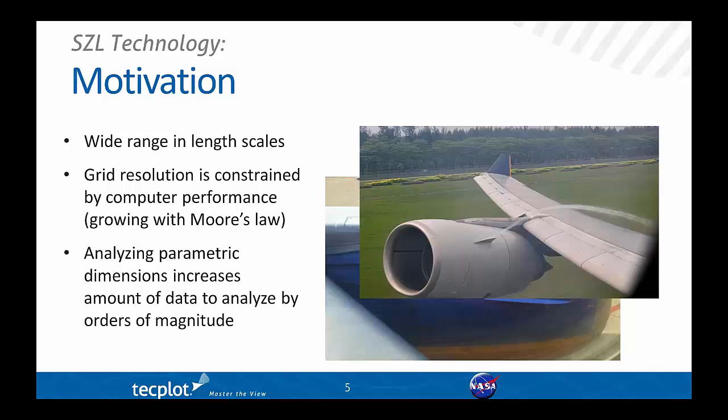And that vortex travels over the wing of the airplane and will suppress boundary layer separation that would otherwise occur because of the wake of the engine nacelle. And the placement of that fence and the size and shape of the fence is critical in order to get the desired amount of boundary layer suppression. Now, this requires a lot of grid to do in a CFD code, because it requires refinement in multiple directions to a very fine grid spacing.